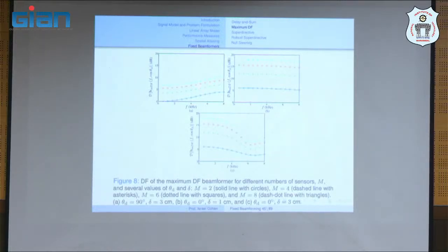So first we see that in these 2 scenarios, when we increase frequency, generally the directivity factor doesn't decrease, maybe even increases. Here it's almost constant. But here, it decreases when we increase frequency. So it means that the maximum achievable directivity factor decreases.